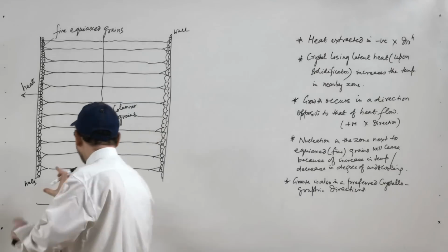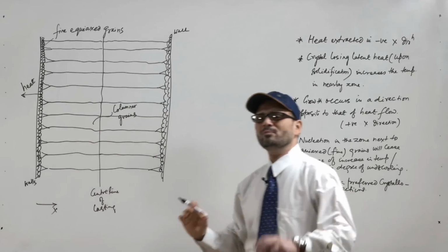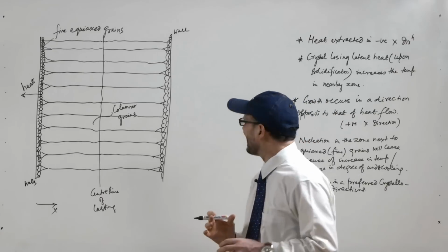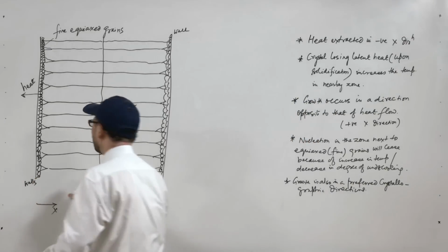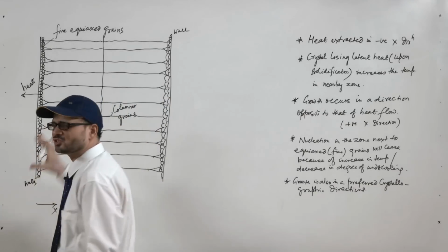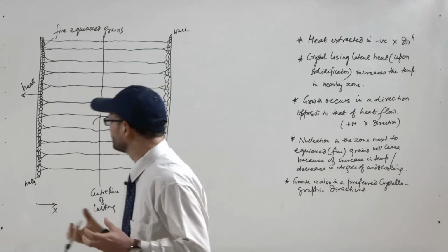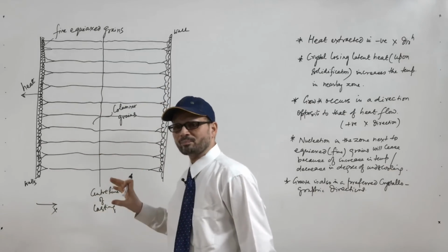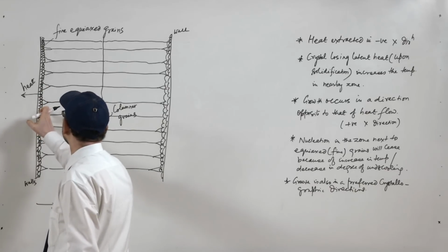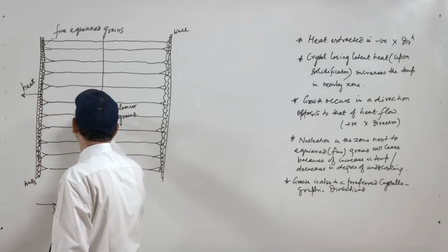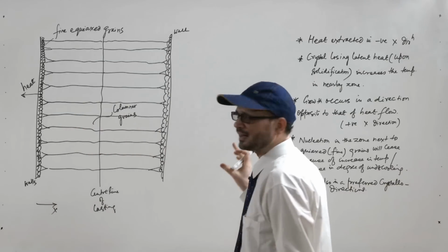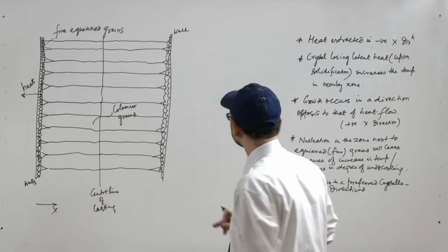And if there is a wall on the bottom also, there will be formation of the equiaxed grain at the bottom of the wall also, as well as from the side also. So, what we see is this is the typical characteristic of the type of grains which are formed in case of pure metals. In case of pure metals, there is plain front solidification, this front advances uniformly and goes till the center of the casting, and this is basically a typical characteristic of pure metals.